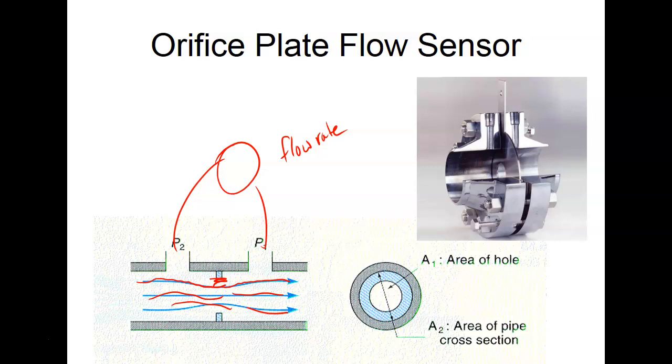You understand? So it's just like resistors. If you have no current flow through a resistor, you don't get a voltage drop. But when you have a flow through a flow control valve, there is a pressure differential between the input and the output. But as soon as it pushes against something and slows down, the flow rate would go down. And of course, when it finally hits the end, we would get no pressure loss because there's no more flow.